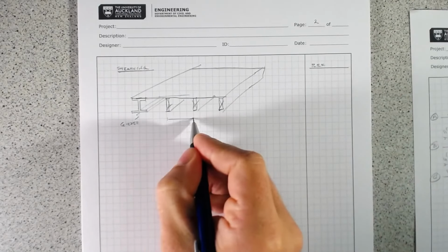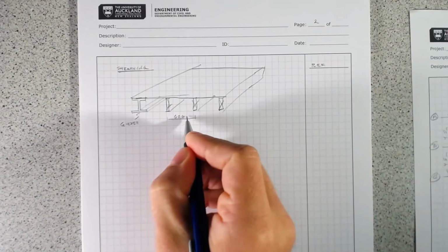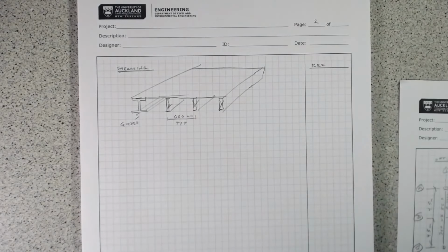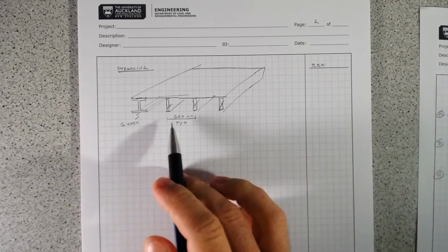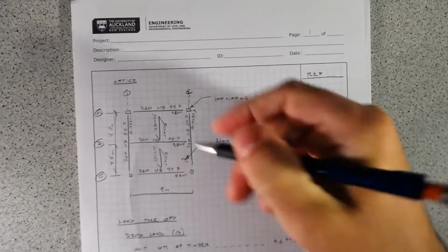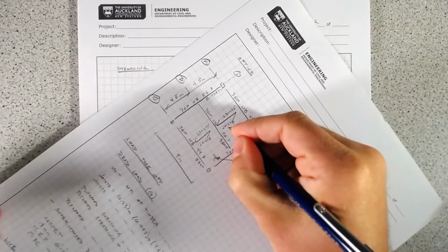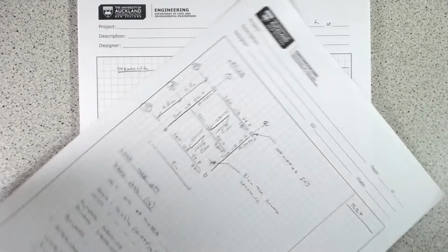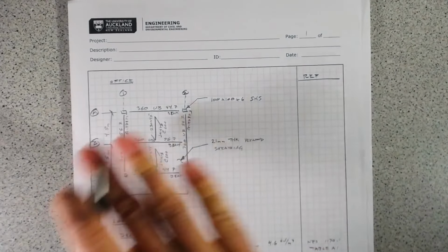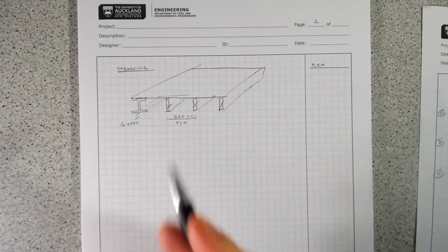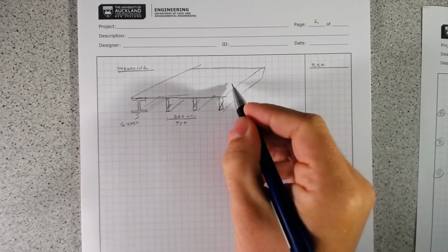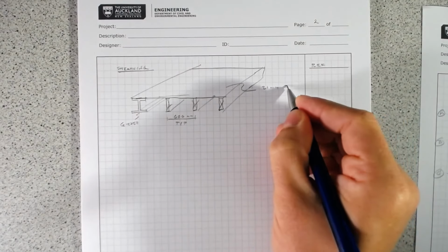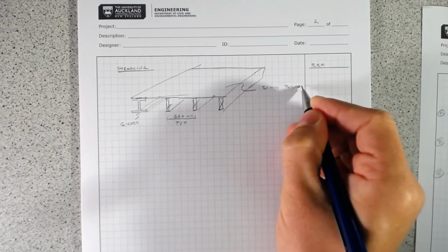And these joists are going to be at 600 millimeters, typical spacing. And in fact, we'll put that up here: joists at 600, just so that we have it nice and clear there. So let's say these joists are at 600 spacing, and then we've got our 21 millimeter plywood sheathing,